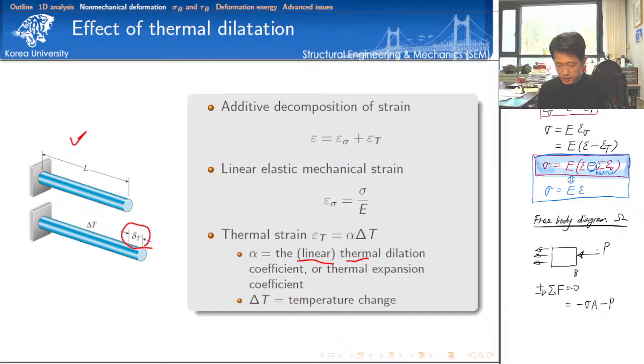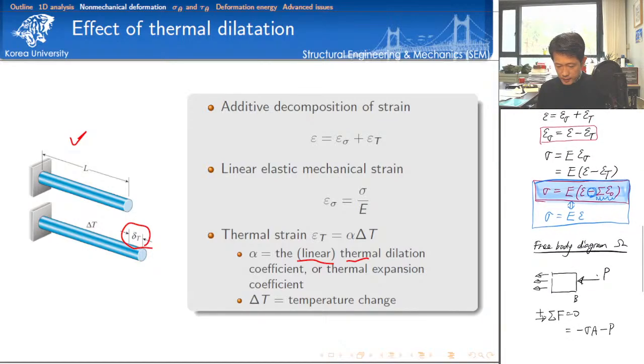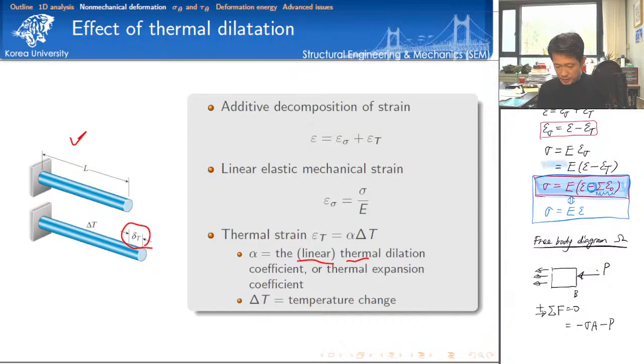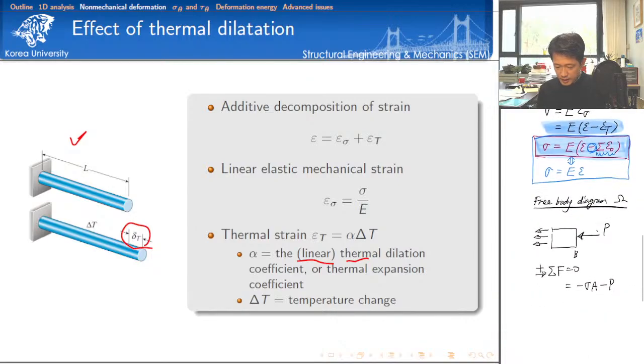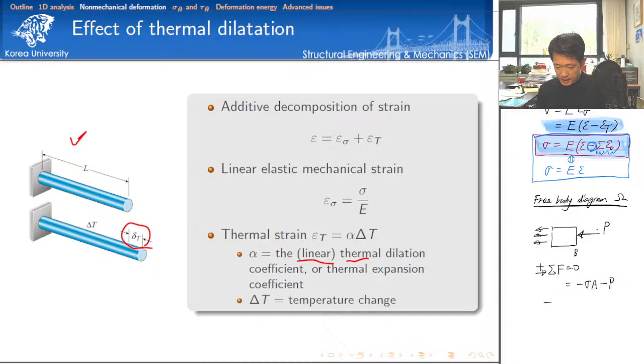This is the information of stress, precisely speaking, we have it here. Let's plug in here. Then minus elastic modulus, and then I have the cross-section area, and then strain minus the temperature strain, the thermal strain. So minus P is equal to 0.